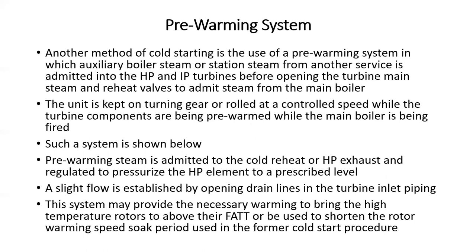There's a little picture of a system on the next slide. Pre-warming steam on this one is admitted to the cold reheat or high pressure exhaust and regulated to pressurize the high pressure element to a prescribed level. We crack some drain lines to get a little bit of a flow. And the system may provide the necessary warming to bring the high temperature rotors to above their FATT or be used to shorten other rotor warming soak periods.